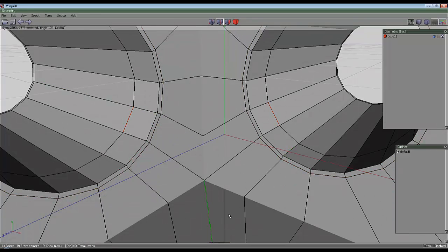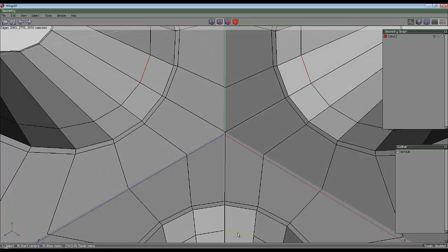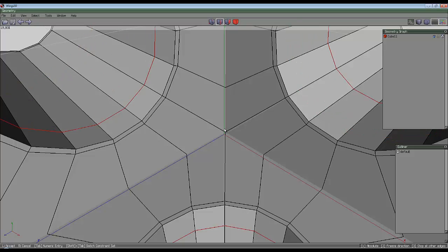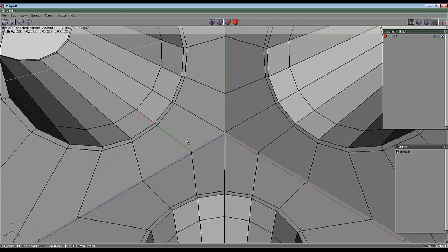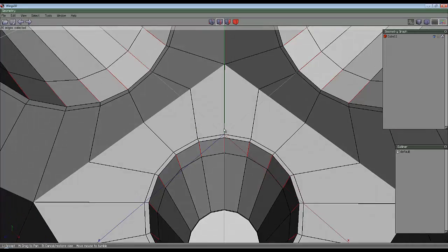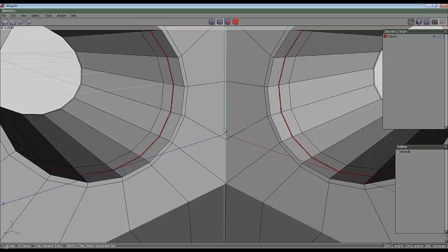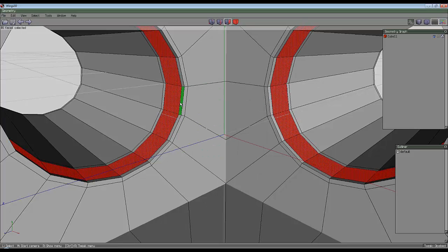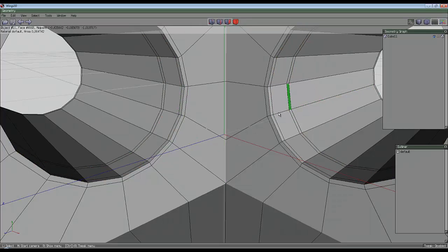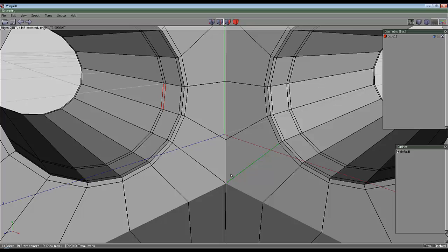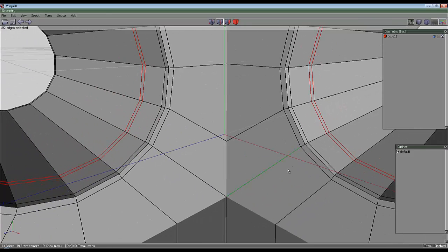Right, if I select these, there's no easy way to move them in that I've found anyway. I might be wrong. I tried the slide command, but some slide out as some slide in, so that's not very helpful. So as an alternative, I'll select that inner edge, I for identical, G, that should just take it around on the inside, check nothing else is selected, C to connect it, and then I'm going to bevel it out. So I've got an inner edge here to match up with that one, and these two redundant edges, so I'll select those two there, go I for identical and delete those.